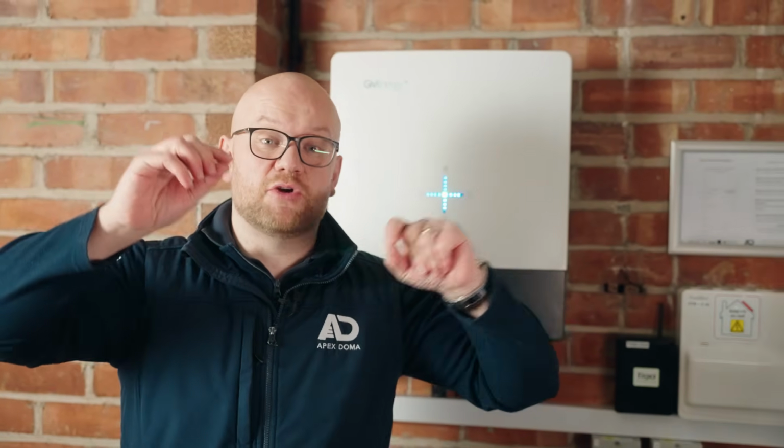Now, if you're running this many cycles and your battery has a 5,000 cycle limitation, it may well mean that the number of cycles you're running might not match the length of warranty that you're in for. If you're making use of a demand flexibility service, or if you're tracking with a thing called an Open API, what that basically enables you to do is access these grid prices. As the grid price changes, you can get a battery and inverter to map to those cheap prices. So let's say it's cheap at 2 o'clock in the afternoon, or it's expensive at some other time. Your battery can import and export flexibly based upon the price on the grid. So something to bear in mind is there can often be cycle limitations.